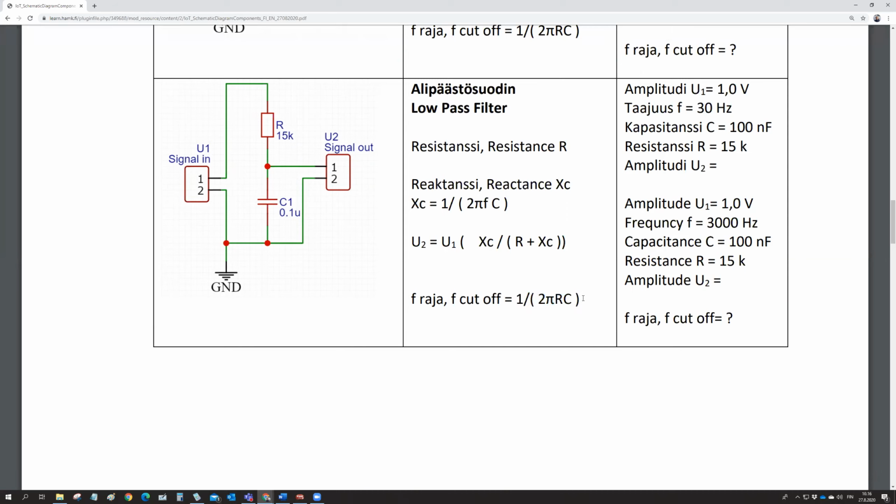And then it's a classical voltage division. Now I have the R1 here, and this is replacing the R2. And then I have the reactance of the capacitance, which is replacing the R2. And then in the classical voltage division equation, the reactance is in here.